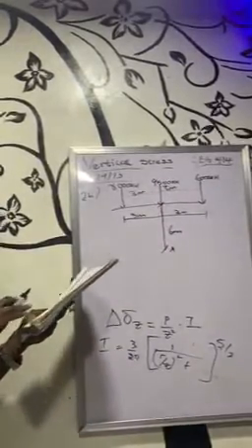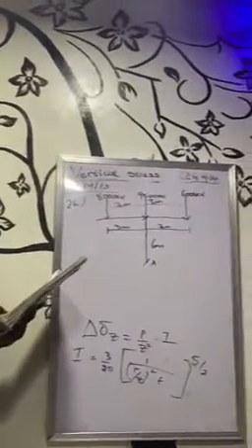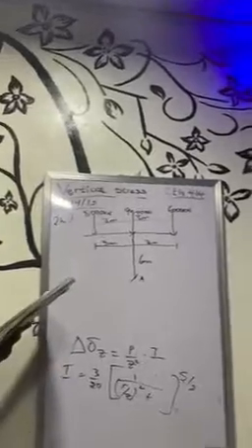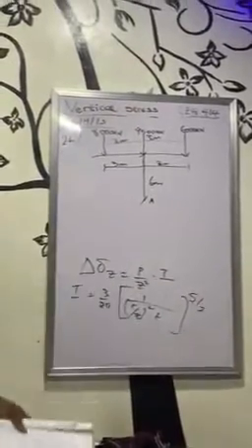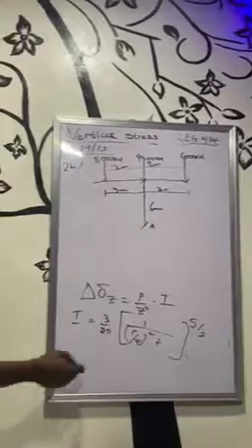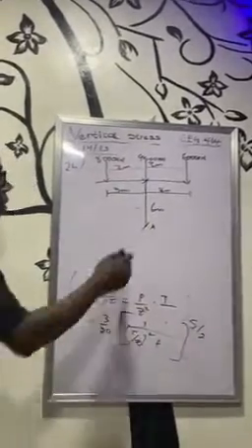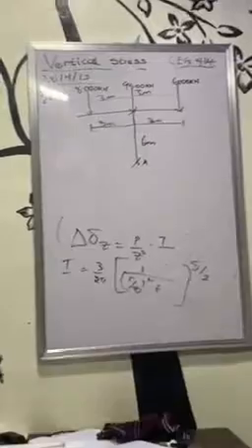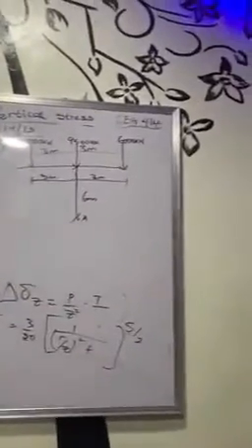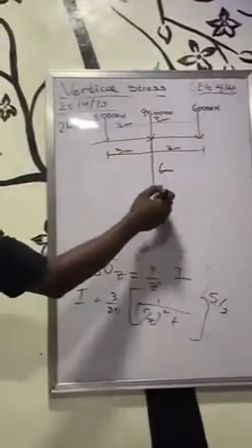Near the surface of a soil mass, calculate the vertical stress at a depth of 6 meters vertically below the center, beneath the 9,500 kilonewton load, using the Boussinesq equation. This is the Boussinesq equation. At a point 6 meters below the 9,500, we are taking vertical stress to this point.